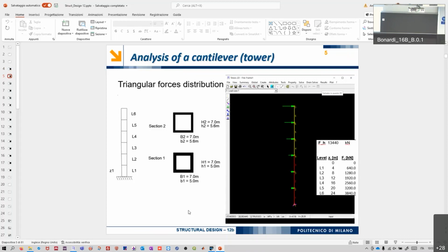The force H, for horizontal, is just the global force that is applied horizontally to the structure, related to the weight of the structure, and it is multiplied by a coefficient that varies according to the intensity of the seismic event we want to model.